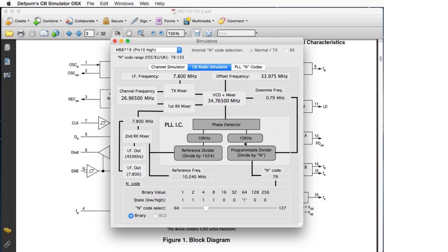That frequency internally is always 10 kilohertz, and this one here is always 10 kilohertz. So therefore they are both the same, they'll be in phase, and the phase detector says that's fine, it won't do a correction voltage. It's then locked, lock detector's okay, so the radio works, and your VCO is on frequency and stuff like that. Okay, so that is how that works in this case.